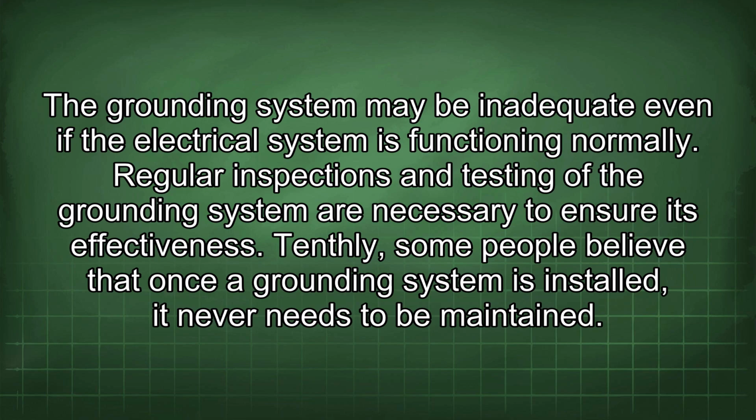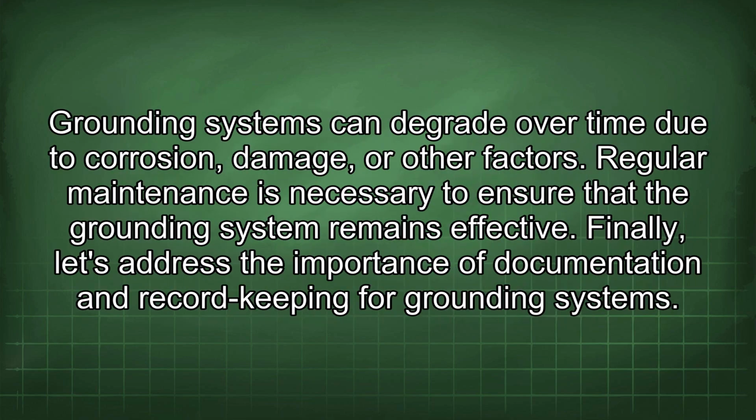Tenthly, some people believe that once a grounding system is installed, it never needs to be maintained. Grounding systems can degrade over time due to corrosion, damage, or other factors. Regular maintenance is necessary to ensure that the grounding system remains effective.